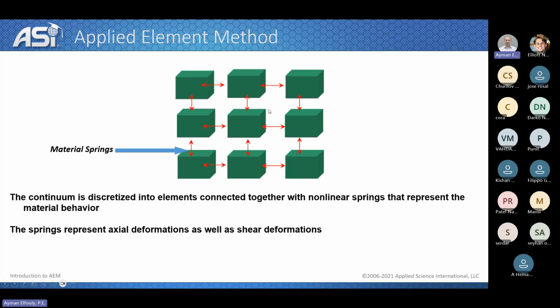So as I said, it is a stiffness based method, and we discretize each structure component into smaller solid elements and connect them together with material springs.